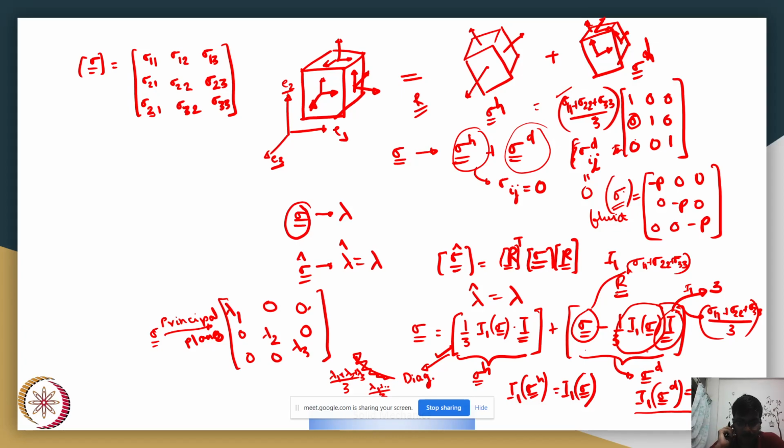So we're calculating shear strain. We have the formula now: 2 times the strain tensor matrix and n vector dot m vector. In that n vector dot m vector, I have to take two perpendicular axes. If I reverse the two axes, like one time I'm taking e1 as n and e2 as m, and another time I'm taking e2 as n and e1 as m, can the answer change? We are multiplying that with 2 times the strain tensor matrix.